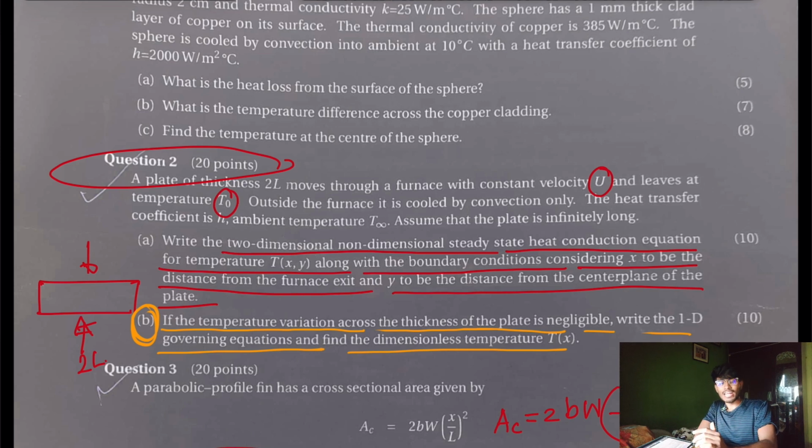And there was an equation where the friction work being done here was equated to the heat convected to the coolant that is passed to cool the clutches, or the ambient air if no coolant is used. Now if you have to do a detailed analysis, you have to consider the whole circular plate and find the temperature distribution in it, and you know that there is frictional heat generation in the friction lining, so this is also a heat conduction problem, right?